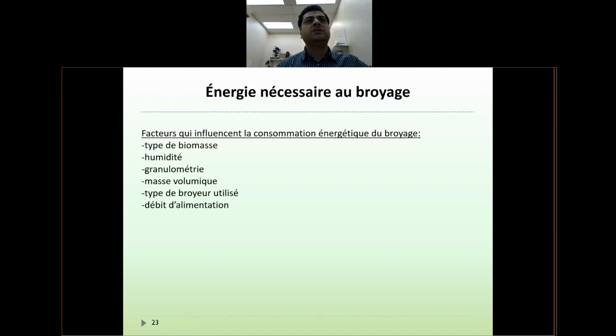So the inlet temperature of the heat source, which is hot air or steam, is usually 300 to 600 Celsius. And usually the energy demand is like 1000 kilowatt hour per ton of evaporated water.